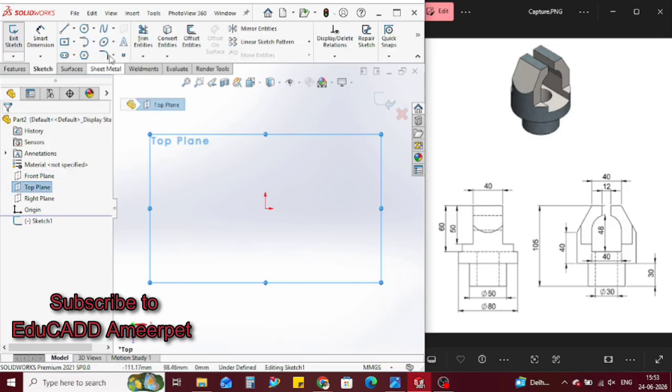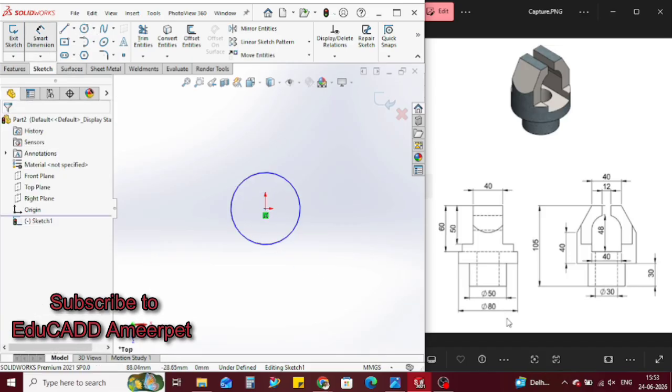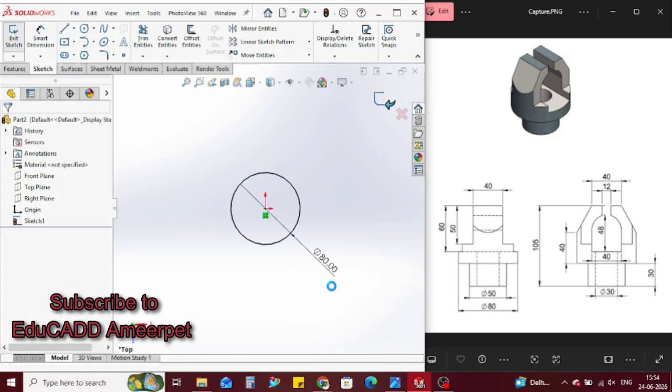I'm activating the sketch here and I'm taking a circular profile. I'm creating the profile with the dimension of this maximum diameter. So 80 is the diameter, so I'm giving the 80 mm. Initially I'm developing only this part, and after that I will extrude this bottom one. Okay, so now exit from here.